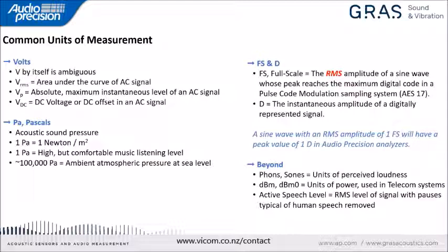Humans cannot hear DC. If you will, human hearing is AC coupled, but we worry about DC offset or volts DC in the output of a device because in a speaker, it uses up travel or range in the speaker, and in a power amplifier, it means you will always be dissipating that amount of energy.